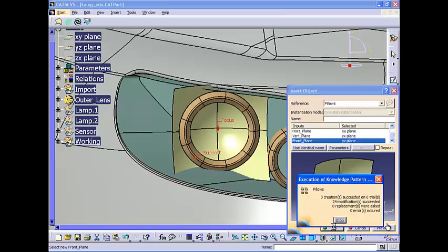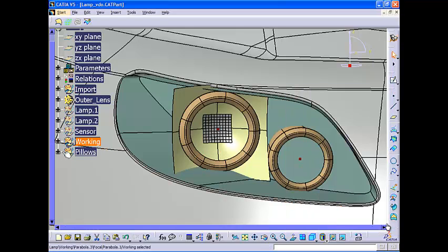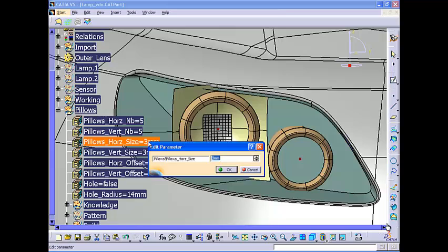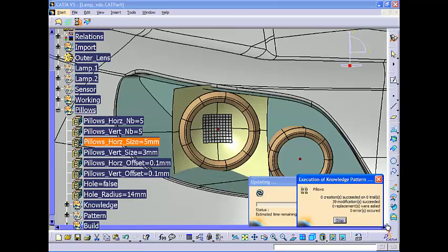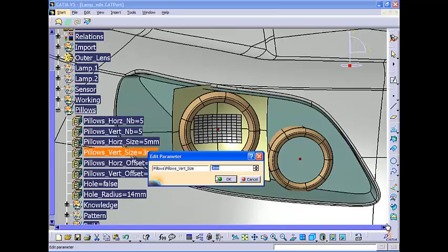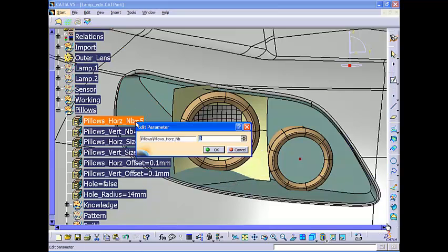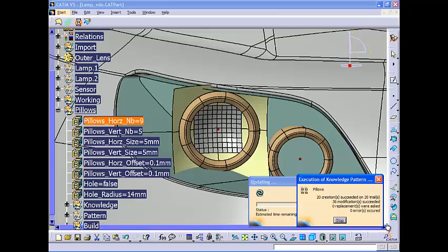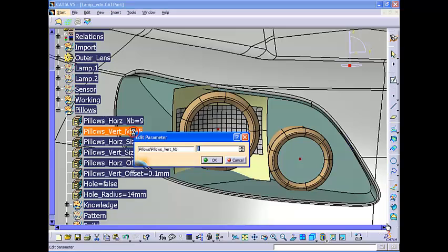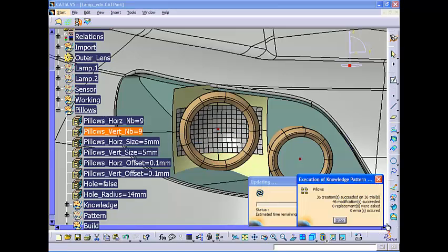The designer then inserts another template to instantiate a geometrical pattern of reflector elements onto the parabolic surface. The pattern is comprised of a great number of reflector elements and is morphed onto the support surface and created in a matter of seconds. You can see there are numerous user-defined inputs such as the size and number of reflector elements, which can be adjusted by the designer during instantiation of the template.